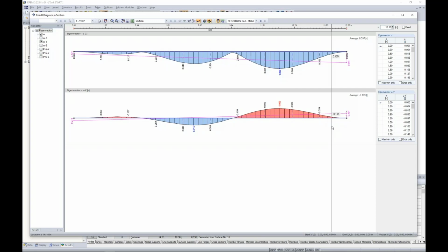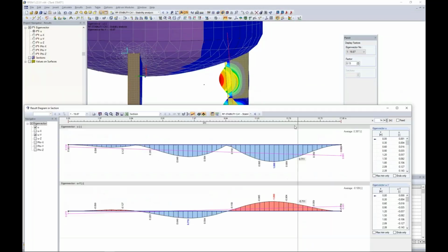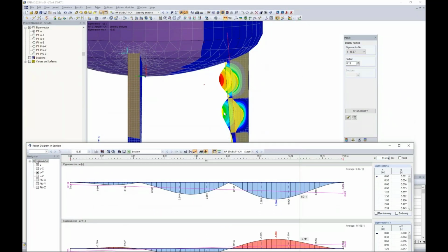Everything that we are modeling within the RFEM program is essentially perfect, and this is true for any general finite element analysis. All lines are perfectly straight, and all elements join together at every FE mesh point, when we know that in reality, lines probably won't be straight and surfaces aren't all in one plane. Mistakes happen, and there are tolerances given for these mistakes.